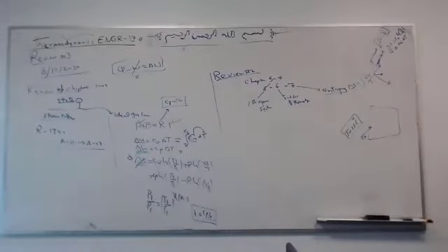Heat capacity for liquid and solid is constant. There is no CP, there is no CV, just one C, like for water. If I want to heat up water from 30 degrees to 70 degrees, C is 4,200 joule per kilogram Kelvin for water, times the mass of the water, let's say you make coffee for yourself, times delta T, 70 minus 30. So you can get how much heat is needed for this water, just pure water, and only pure liquid. It's not steam, it's not vapor and liquid.